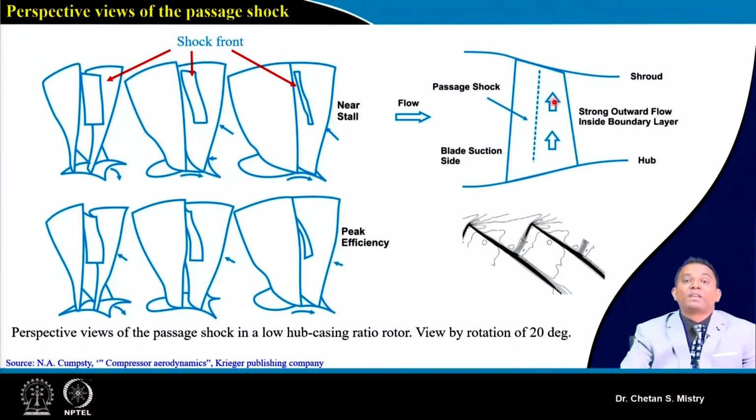So this is what is representing the movement of my flow on the upward side. So this is what will be creating trouble near my tip region. We can realize we are having the differential pressure on pressure surface and suction surface, that's what will be giving my tip leakage flow. Along with that we are having shock flow, and that's what will be creating a whole lot of trouble to the flow in the tip region.